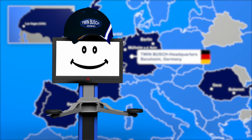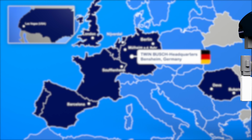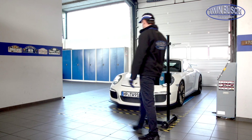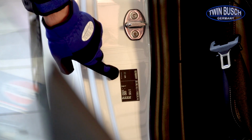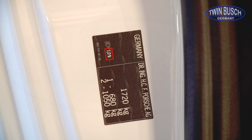I will now show you our headlamp tester TW SWE-A. We will now show you how the device works in principle. First of all, to do this we need the angle of inclination for the vehicle headlights. This value is usually indicated on the door frame or also directly on the vehicle headlights.